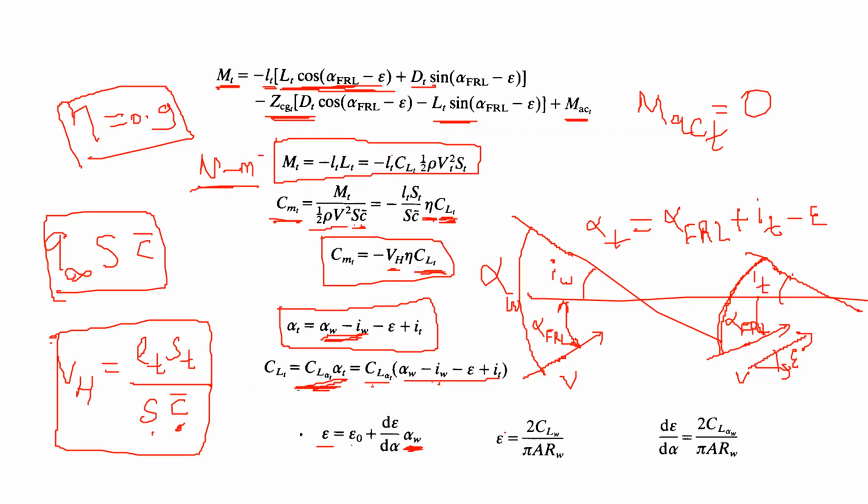All right. So now this epsilon has this expression, and when you take the derivative, then this CLW becomes CL alpha W. So it was the actual coefficient of lift here, but it is the lift slope here. So you have the expression for this. Now, what is the number epsilon naught? This is the downwash angle at zero angle of attack, and this is for other angles.